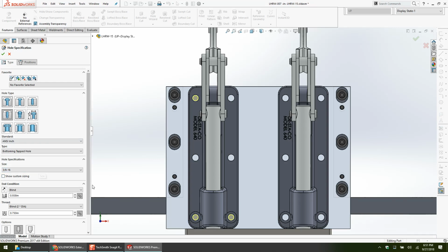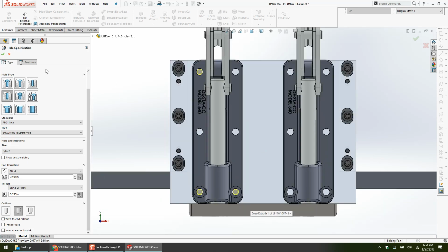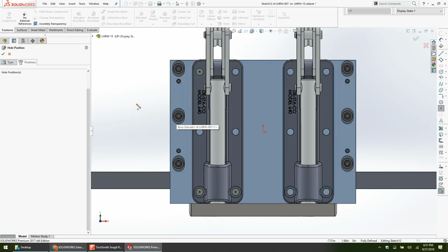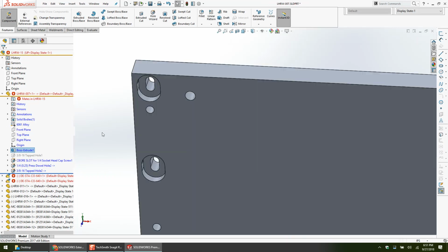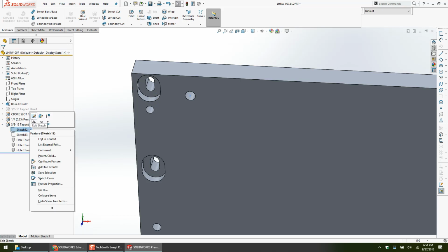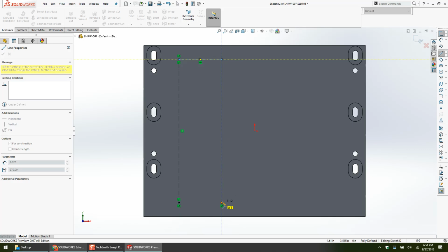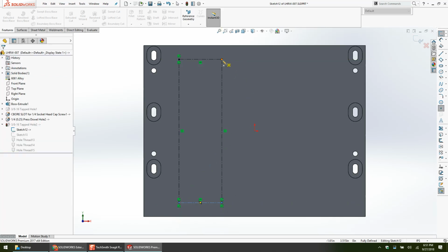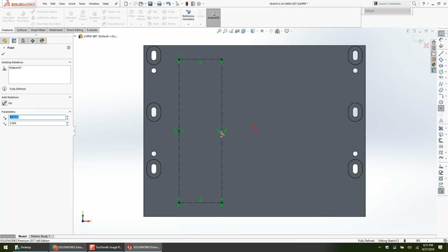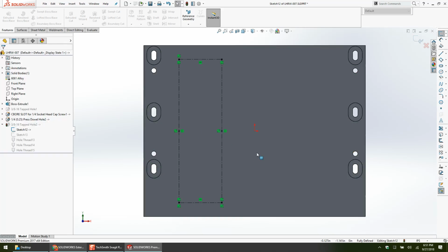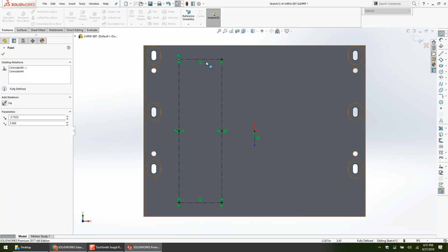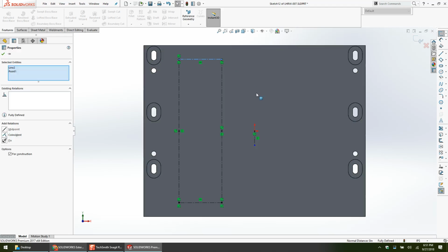3/8-16 looks better. All right, why did I only put 3 holes in there? Because the rest of it is geometric. So now I open the part file, edit that hole wizard sketch, draw construction lines, and I can very easily drop in the rest of my holes. How many external references do I have for this whole pattern in that assembly? 3. And then, because every good designer puts the origin at center mass, who's heard me say that before?